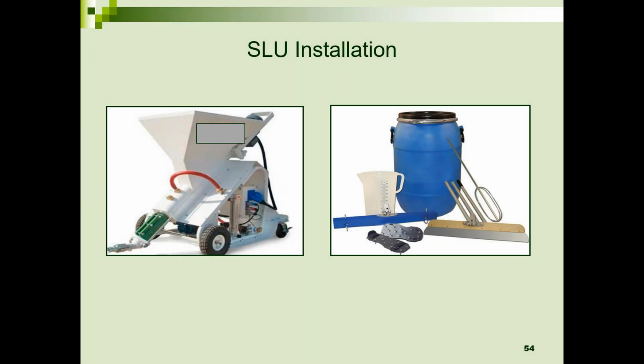Now, as far as installation, you can mechanically mix the product as we see on the left, or barrel mix it. Both methods are acceptable. We've got contractors that love either system and work very well with it. The mechanical application might be beneficial where you have a large open floor area. There's no walls or other transitions. You could mix and go and get it all done in a hurry, so to speak.